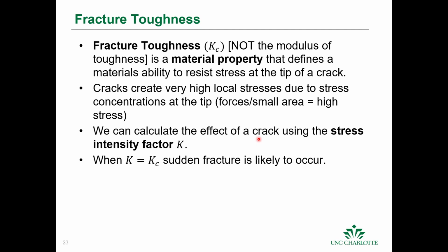And we can compare that to the fracture toughness, and when the stress intensity factor, which is not the same as the stress concentrations. So it's really important in this class and with materials that we get our language correct. You know, stress concentration, we're talking about geometry, changes in cross-sectional geometries, which cause stress risers. It's not the same as the stress intensity factor K.